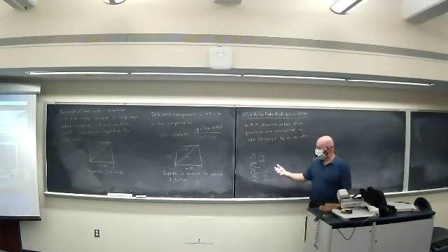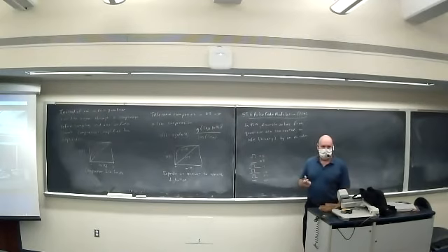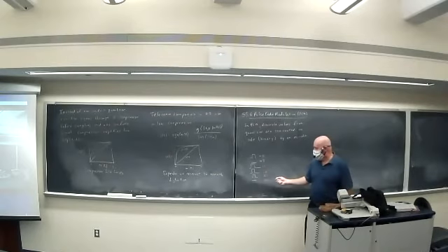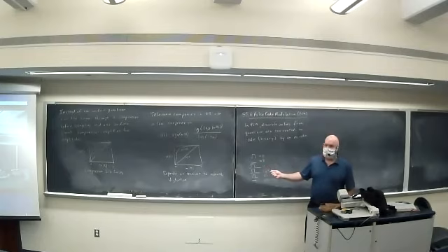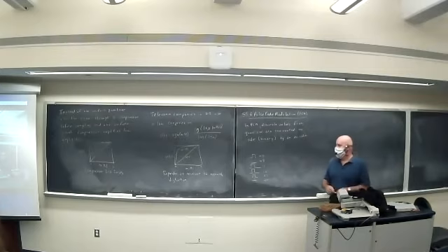We'll see that my required bandwidth is proportional to my pulse width. The wider the pulse, the smaller the required bandwidth. It doesn't depend on the amplitude of the pulse at all, though. So by using 4 different amplitudes like this, I can get double the pulse rate. Now, I showed amplitudes here because that's the easiest thing to think about at this point.